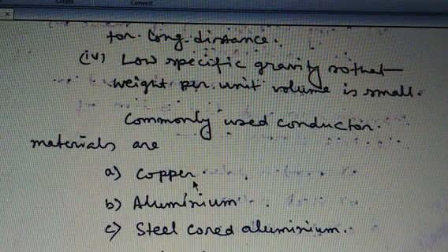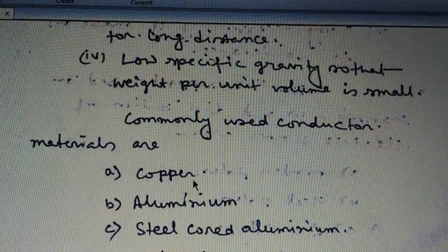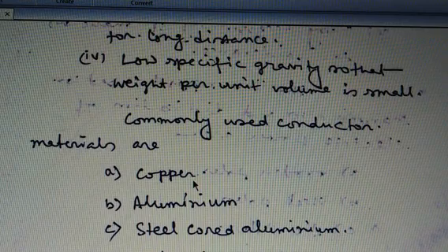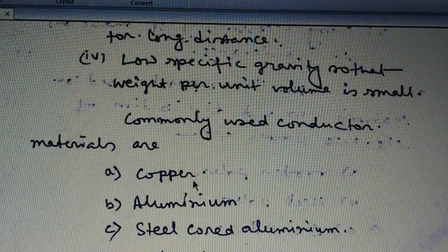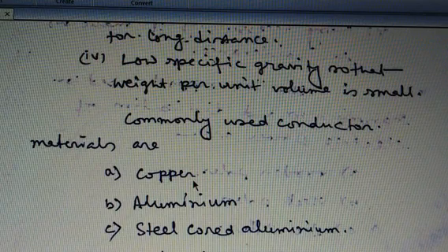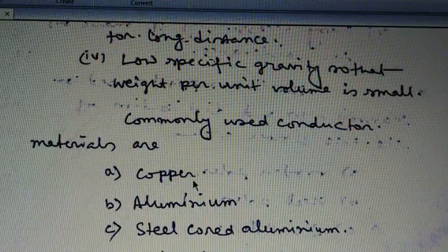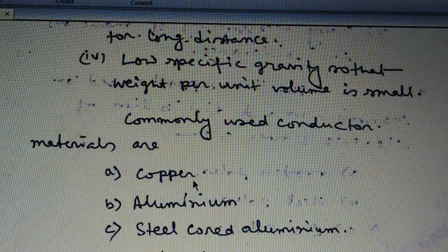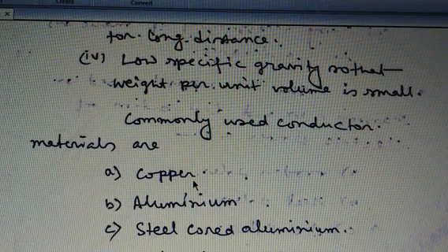Firstly, the cross-section area of the conductor is smaller, and secondly, the area offered by the conductor to wind load is reduced. Moreover, this metal is quite homogeneous and durable, and has high scrap value. There is hardly any doubt that copper is an ideal material for transmission wire, but the main disadvantage of copper is that the cost of copper is very high. So nowadays we tend to use aluminium in place of copper.